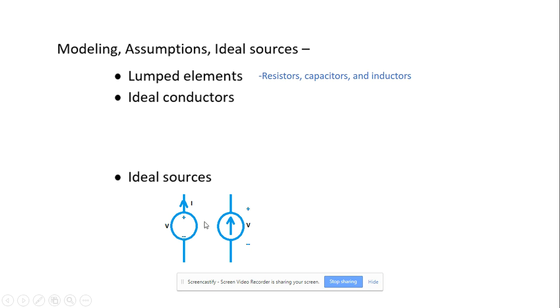All right. Again, note, when I talk about sources, I'm not using passive sign convention because I have the current leaving the positive instead of entering. I have the current leaving the positive terminal that I've defined the voltage across here, right? So not quite what we previously discussed, but this has to do with DC power. And we're about to discuss that after I get into a couple of examples for Ohm's law. Okay, so as we get into these examples, what's important is, how are the voltage and the current defined with respect to the resistor, or with respect to the passive element, right?